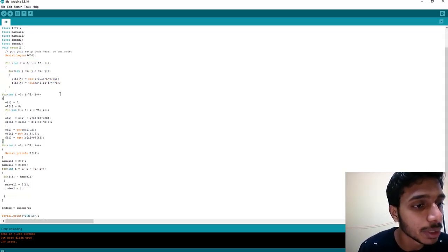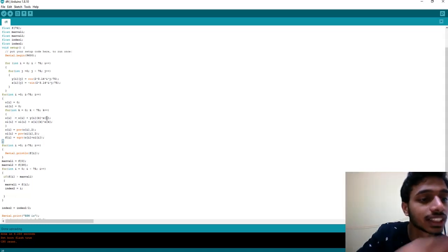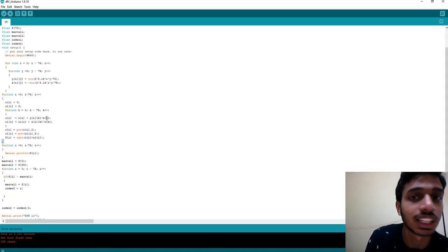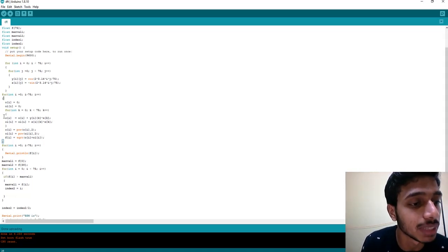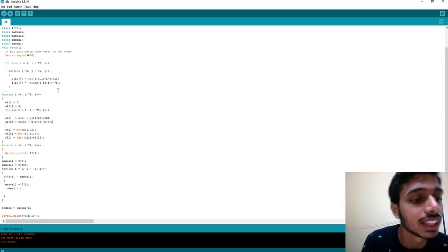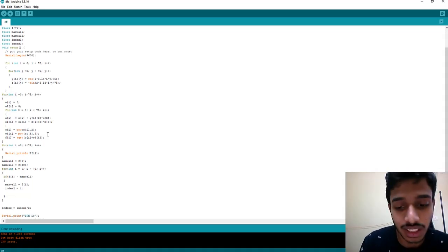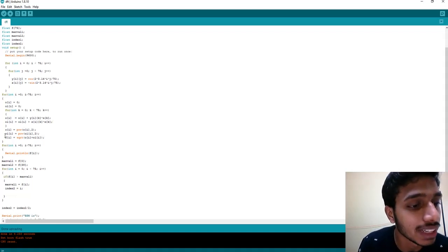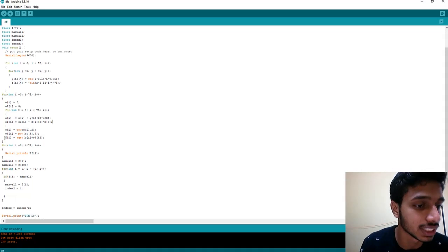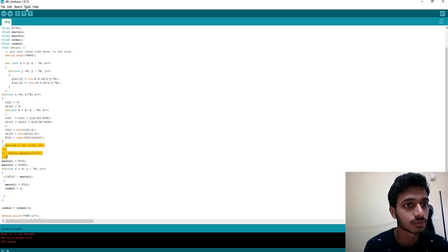So next what I will be doing is multiplying this with the input signal. As you can see here, I'm multiplying Y with the input signal and again adding this. I'm iterating this loop. The number of times I'm iterating this loop is equal to the number of elements. So thus I'd be completely multiplying every element with the input signal in this matrix. This will be followed by squaring and adding to get the magnitude spectrum. At the end, I would be requiring the magnitude spectrum only. So I will be storing the magnitude spectrum of my input signal in F of i. So let us see how this magnitude spectrum looks like.